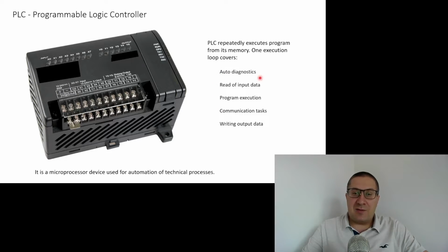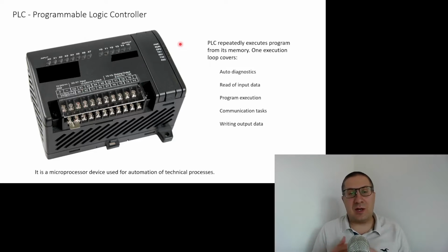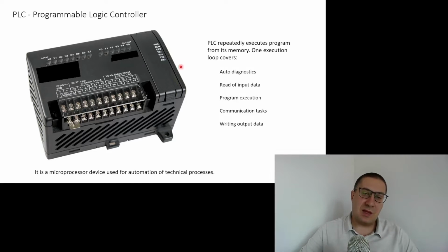So first we'll have the auto diagnostics, if everything is all right with those cables, with those values, with the memory, with the PLC. Then we will read the values from inputs, execute the program, also send the values to other controllers, because usually we have more than one PLC controller in the factory.